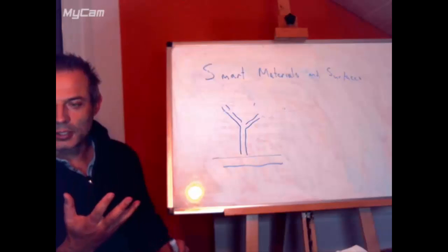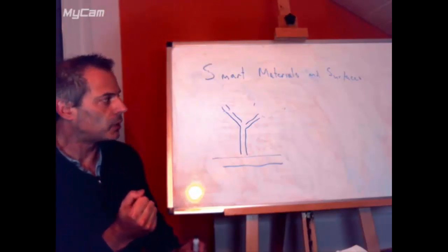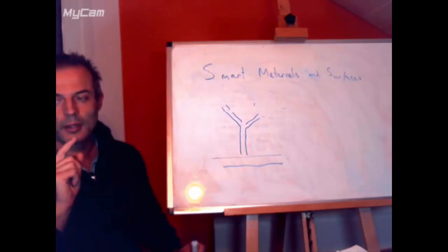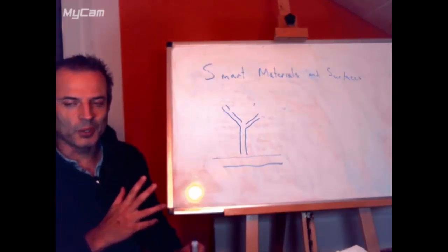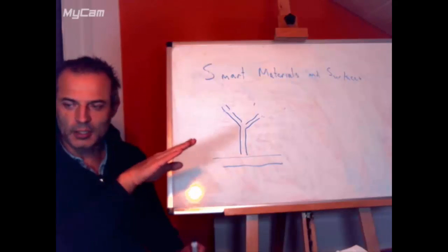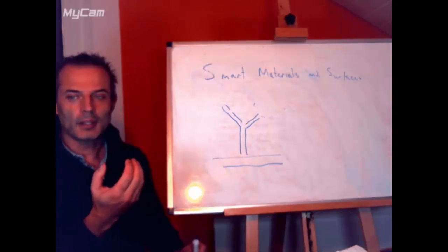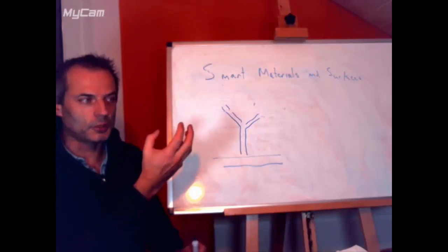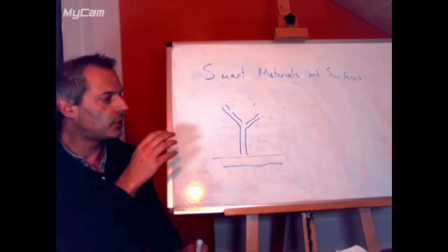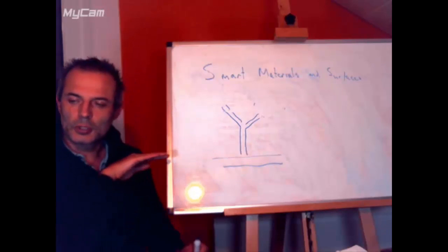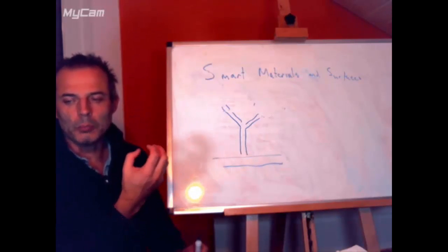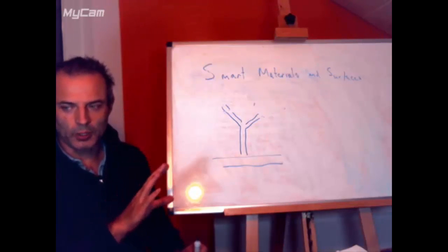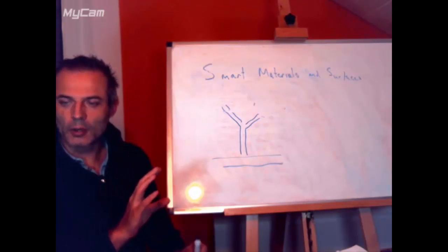If this surface is a cantilever or a quartz crystal microbalance, something that works in a liquid, which is a problem for both of them, because if we have a cantilever and it's bouncing up and down, that's difficult because it will be held back by the viscous resistance of the water. If we have a quartz crystal microbalance, then it will be measuring the water on it as well as whatever we want to apply. So there are problems.